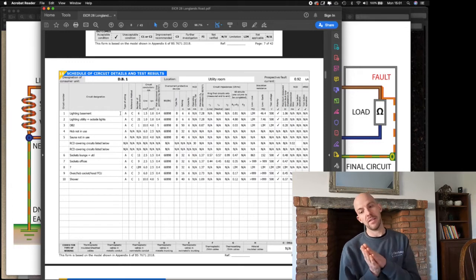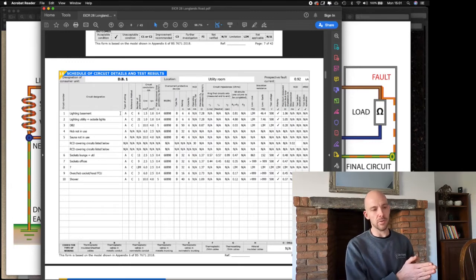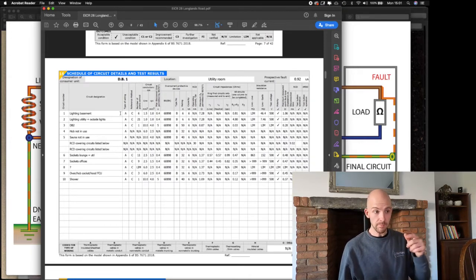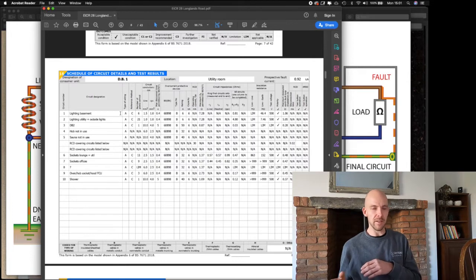And again, the way that the cable has been installed will dictate how much current can flow in that cable before the cable overheats. So if we suspect that an undersized cable has been run through insulation that's supplying an electric shower, a very current hungry piece of equipment, we might recommend that that's investigated further to make sure that the cable is capable of supplying the shower.